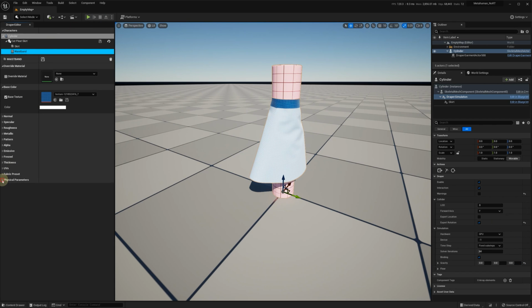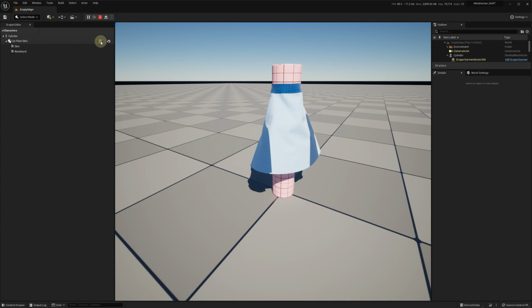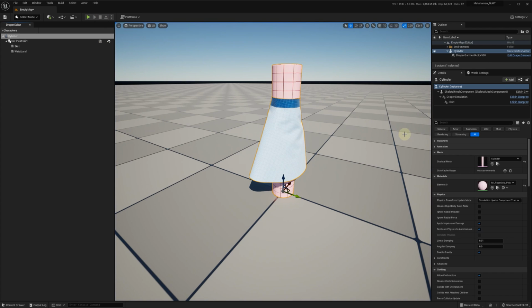When binding is turned off, either by using Shift-B or setting the binding tolerance to 0, we can adjust the garment position and save the garment. After that, binding will be applied to this new position.